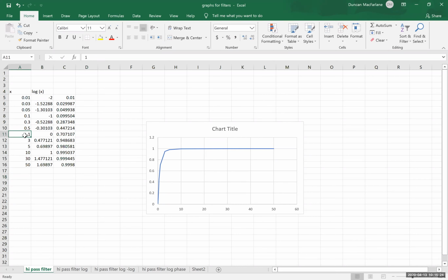And so what I'm going to do for this is plot 2 orders of magnitude below it and 2 orders of magnitude above it. So if this were a kilohertz, then I'm going to go down to 10 hertz, and I'm going to go up all the way to 100 kilohertz. So I'm including 4 orders of magnitude in this plot.